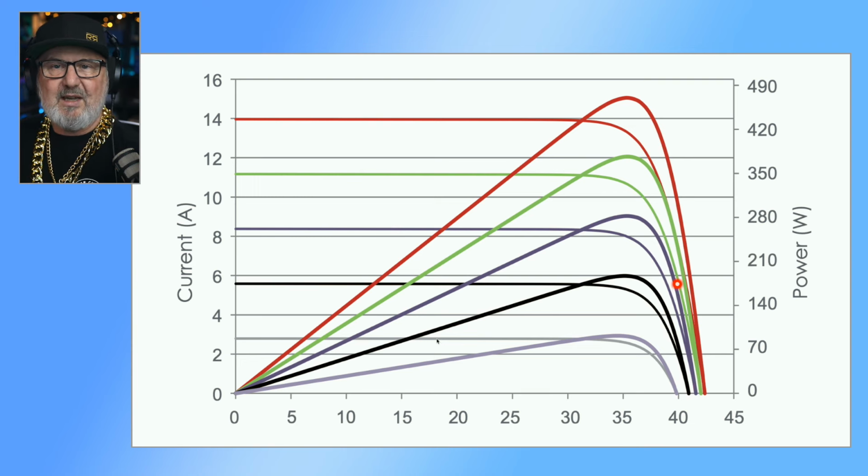So it keeps tracking along the IV curve going, volts times amps equals power. Am I getting more power? Yes. Keep tracking along this line. More power? Yes. More power? Yes. More power? Yes. Oh, less power. I've gone too far. Go back. More power? Yes. More power? Yes. Less power. Oh, too far. Go back, right? So it's tracking back and forth, literally, doing a little